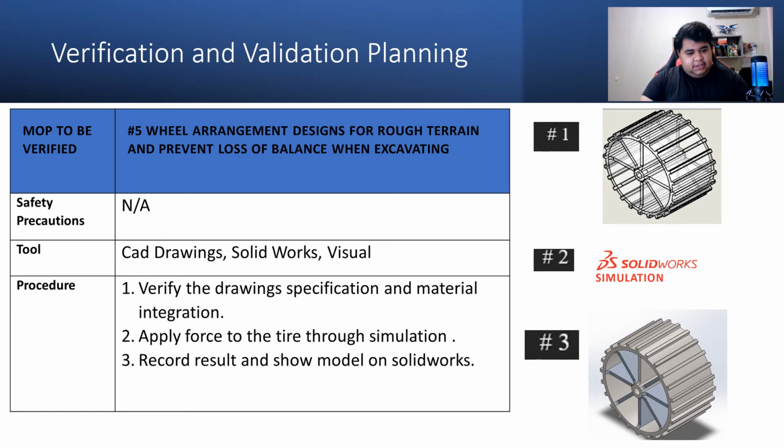A lot of wheels are sometimes made of PVC or aluminum 6061. Here, the interior rim is aluminum 6061 alloy to help strengthen the main parts of the wheel, and we'll be using less material. The spikes will actually be part of the aluminum, and they will help when the rover is moving. They will keep the rover from tipping over going through rough terrain.